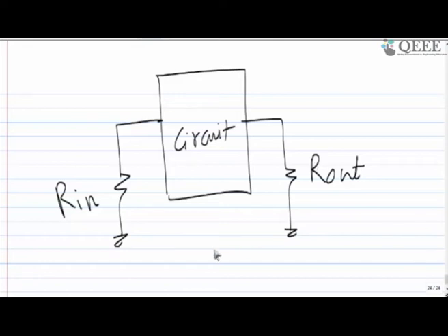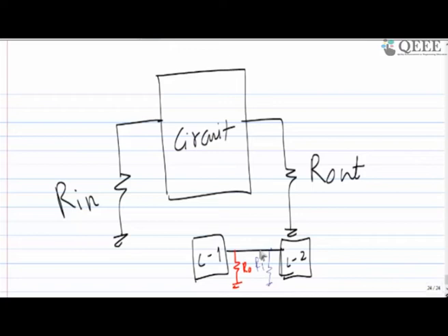If you are connecting two circuits, let's say circuit 1 C1 and circuit 2 C2, and I connect both directly, what will happen? The output resistance of C1 and the input resistance of C2 will be in parallel, and they are going to affect the potential which is available here, right? This is one keynote I want to tell.